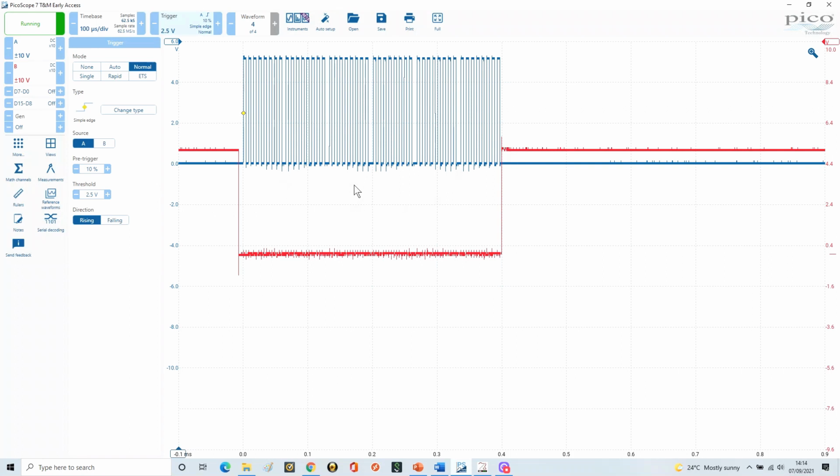And if I had a 3 or 4 channel scope, then I would be using this chip enable as really my primary trigger, so I can look at everything relative to that edge. But because I've only got a 2 channel scope, I have to decide what's the most important thing in this case. And so this is where you can actually select your sources, either source A or source B, in this case, to decide where your priorities lie and what you want to see. So I hope that's actually made sense and you've seen it from a digital perspective.